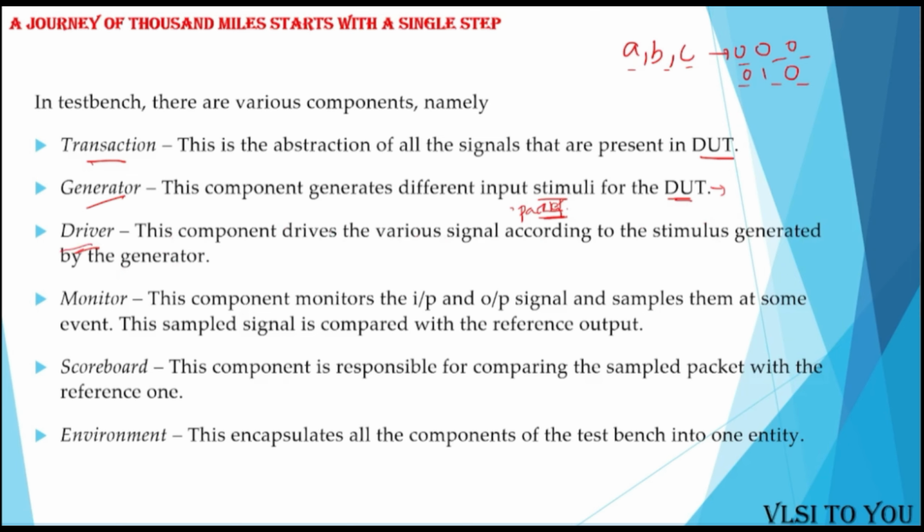That means whatever stimulus the generator is generating, it will be driven to the DUT by the driver. Now what does the monitor do? This component monitors the input and output signals and samples them at some event. Okay, this sampled signal is compared with the reference output.